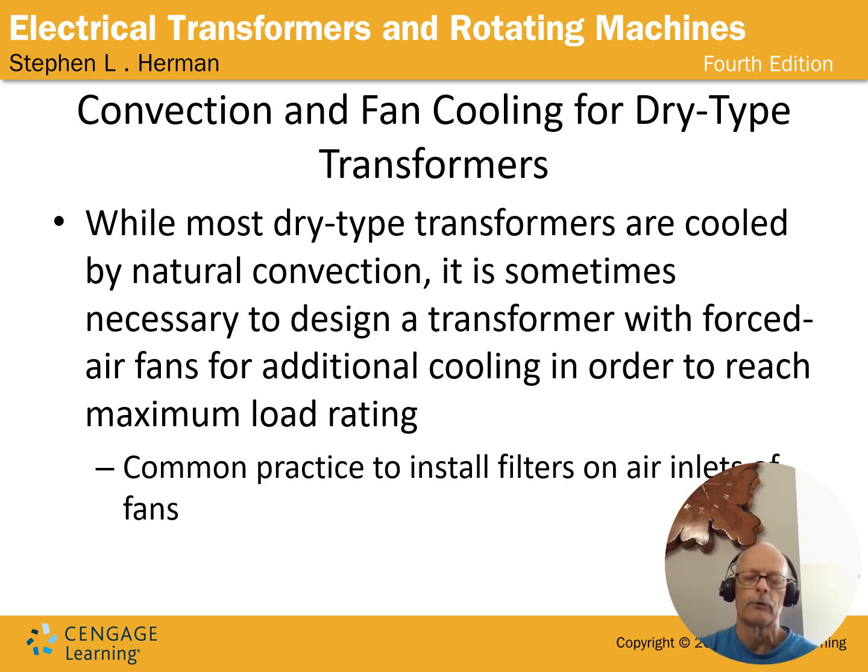Always remember to de-energize and check and triple check your voltages going to your transformer before you PM them. We throw that in there because I've seen people get distracted for a moment when they're supposed to disconnect a load or a circuit, and they stand there with their tool in their hand and forget they hadn't already done it, and they go back to work.